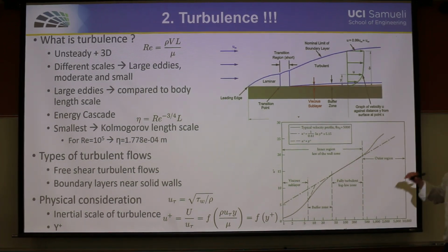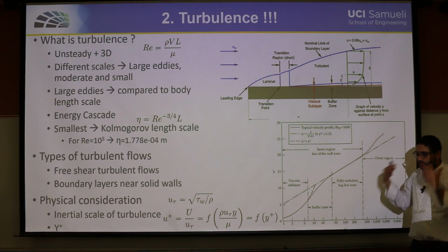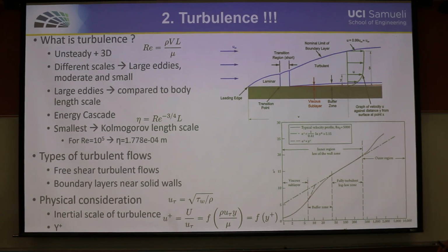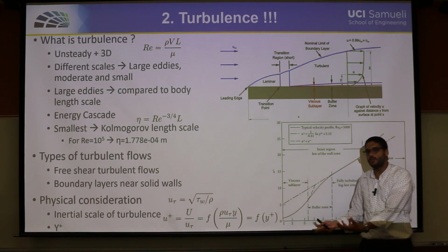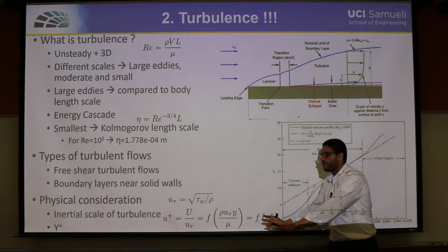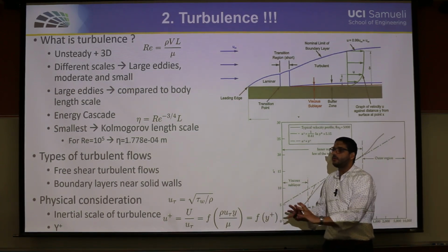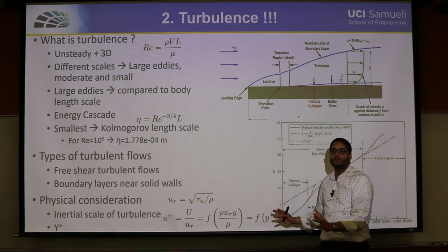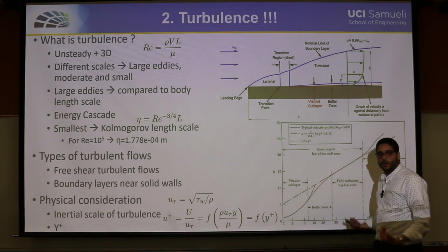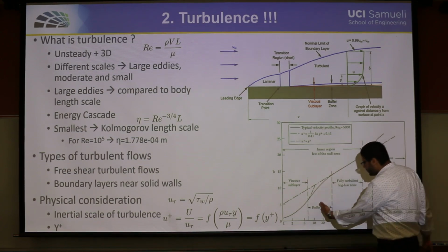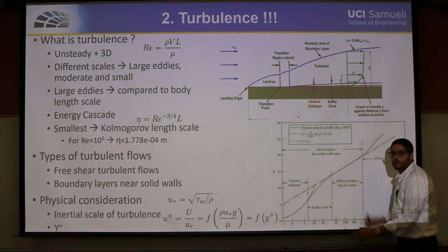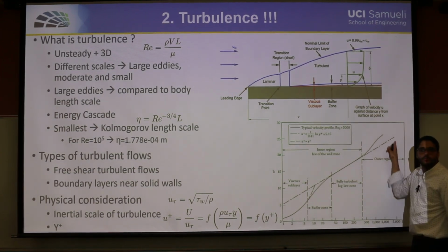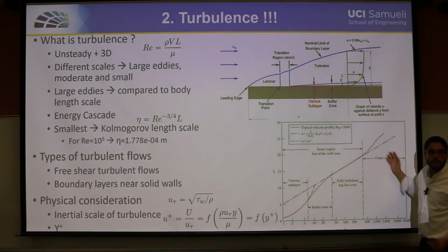Why am I emphasizing this so much? Because if we are having a turbulent CFD simulation and we are solving that flow field, regardless of the way that we are trying to resolve the turbulence, our CFD code must satisfy this y plus, because this is pi. You cannot draw a circle without satisfying pi. I don't care how you are drawing it.